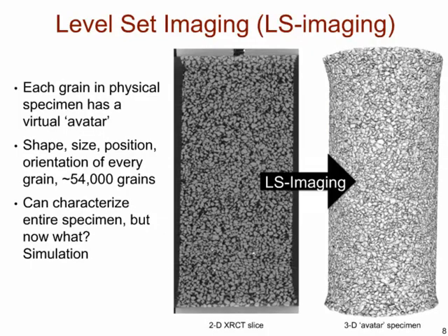So the big vision here is that we would like to go from an image onto a full model of a specimen, and we would like to make the first direct comparison between a triaxial sample of sand being sheared as we're taking pictures of it, and modeling the exact same triaxial sample with the same particles, because we know each of the particles from the X-ray CT, and the same boundary conditions, the same radial pressure applied to the membrane, and the same axial deformation.